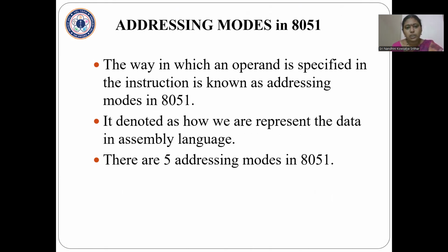Next, we are going to see about the addressing modes of 8051. What is meant by addressing modes? The way in which an operand is specified in the instruction is known as an addressing mode. It denotes how we represent the data in assembly language. And thus we have 5 addressing modes.